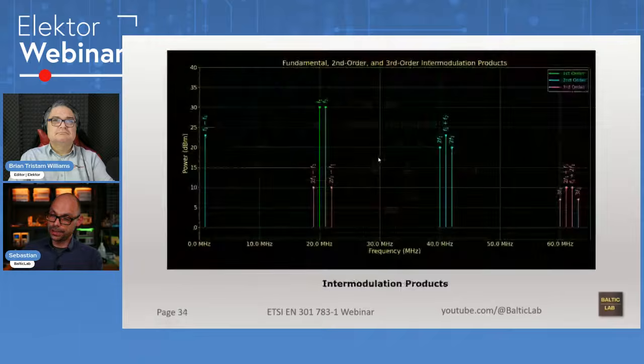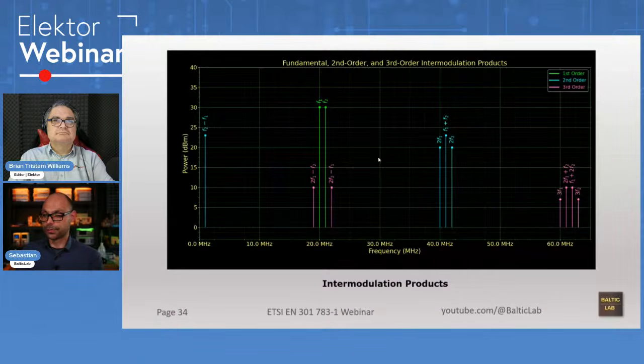What's happening here is, and this is just an old graphic from me about intermodulation products, anytime you push more than one signal into any nonlinear system, be it an amplifier, a mixer, or anything of the like, all those signals are going to mix with each other. Now you might say, well, I'm only putting a 145 megahertz signal into the device. You're not. You're pushing that signal and its harmonics into the device. They all mix with each other. And this disaster here is only graphed up to the third order intermodulation products. There's a whole lot more of those.